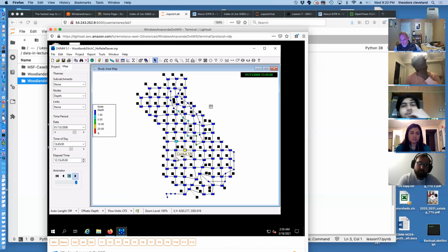In our ICPR quasi 2D model that we just built, there's no way for water to get out of that cell other than evaporating or infiltrating. And if this is the as-built or current conditions, then the design engineer is presented with, how do I get water out of here, given that there's no way anybody is going to give me a permit or allow me to bury those houses in 6 feet of cement stabilized soil, because people in Texas don't like to go downstairs to get into their house.